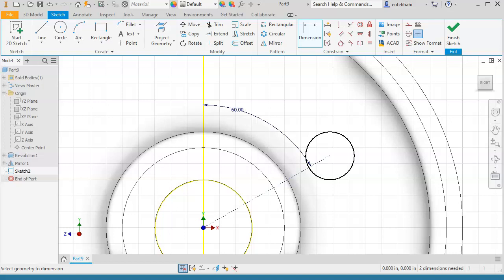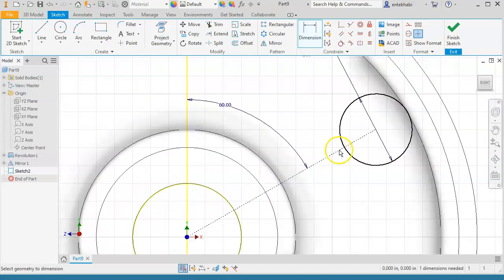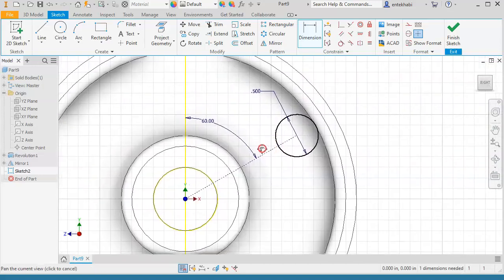Now we need to add the diameter and the length of that line, which will be equal to the radius of what we call the bolt circle, which locates the hole. That's the term we use, bolt circle, for defining the location of those holes in the flange, or pulley in this case.